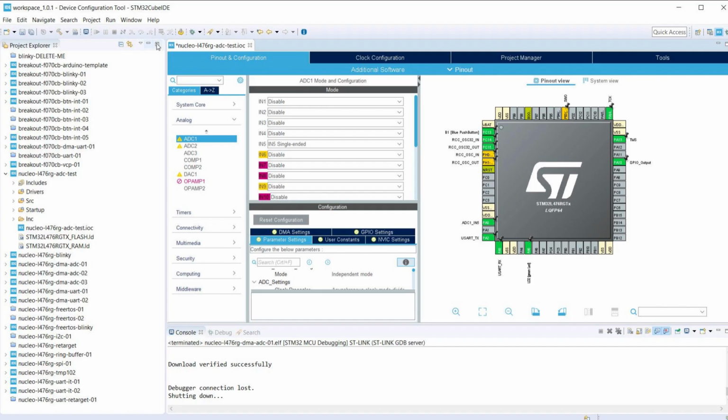It just hangs out until it's done. Pretty much. Once poll for conversion returns, meaning the ADC is done, you call HAL_ADC_GetValue to retrieve the digital result, that number, maybe 0 to 4,095 for 12-bit. And then if you're in single conversion mode, you might call HAL_ADC_Stop.